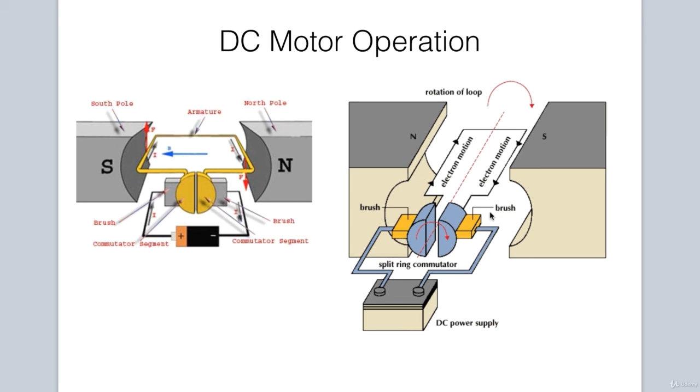To change the direction that our motor spins, this process is simple. You just change the polarity of the power that you apply to the terminals of the motor, and it would spin in the opposite direction. The trick is, how do we control this and make this happen for our car project? That is where the Arduino comes in. We will address this some more in the next lecture.